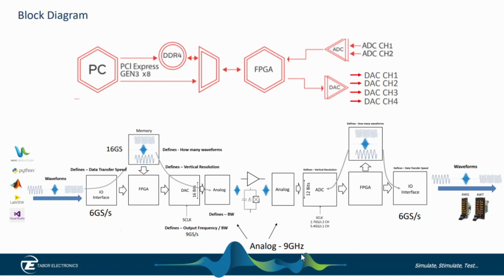We have the analog bandwidth here of 9 gigahertz. So we allow you to use this 9 gigasample clock in both the first and second Nyquist zone. I've done experiments and I've used it in the third Nyquist zone. The roll off of this filter is very slow, so 9 gigahertz is not a hard stop. Then on this side we have a 12-bit ADC. It goes into the FPGA, you shove it up into memory, and you can push it back out to do analysis or make decisions. Or you can make decisions just internally inside the instrumentation using the FPGA decision blocks, as I just talked about.